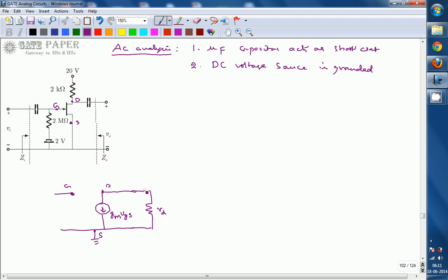RD is going to be a resistor. So this is the drain, this is the gate and this is the source. So this is the circuit diagram, the internal circuit diagram or small signal model, for the given JFET. So we can write this as VGS, plus minus. Okay. Now we have to add the other circuit parameters.